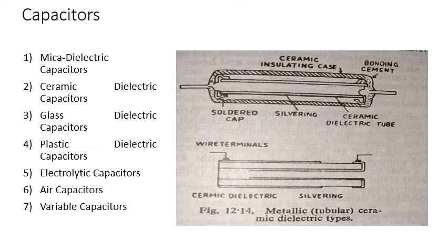In the rolled electrolytic capacitor, the anode consists of a long strip of aluminum foil carrying the oxide film on both sides. The ammonium borate electrolyte solution is held in an absorbent paper tissue strip of similar length. A second strip of aluminum foil with no oxide film lies next to the paper tissue and acts as the cathode. These three strips are rolled tightly together as in a rolled paper capacitor and provided with an outer cover of aluminum.